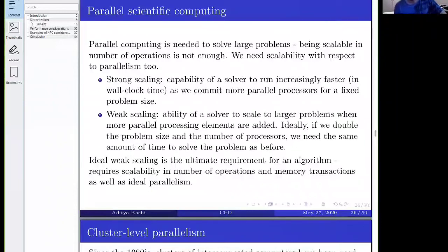Would you be able to use Crank-Nicolson? Yes, you could use Crank-Nicolson, but there is no point. Because we are trying to solve a steady state problem, we just need to damp the high frequency errors or to just converge the nonlinear problem. So because of that, we don't care about the accuracy in time. We just need to get to the steady state. We just care about the accuracy in space for these problems.